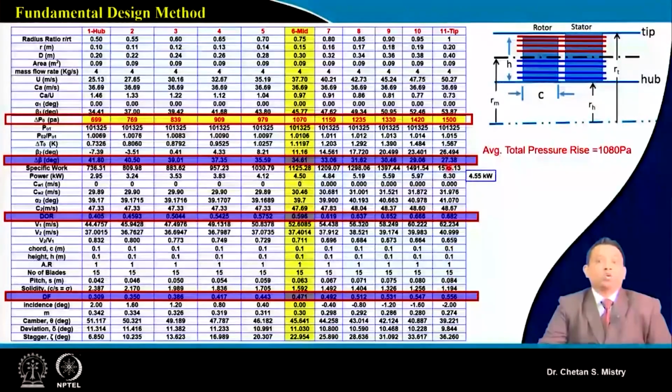So you need to have two observations. First, near the hub region, and second, near the tip region. Now, when you are doing your iterations by putting in different numbers, it may be possible that near a mid station you will have some kind of droop, or maybe an upside kind of trend. So just adjust that number. It is the designer's choice, it's your choice, you need to decide on that number. That's how these numbers are selected.